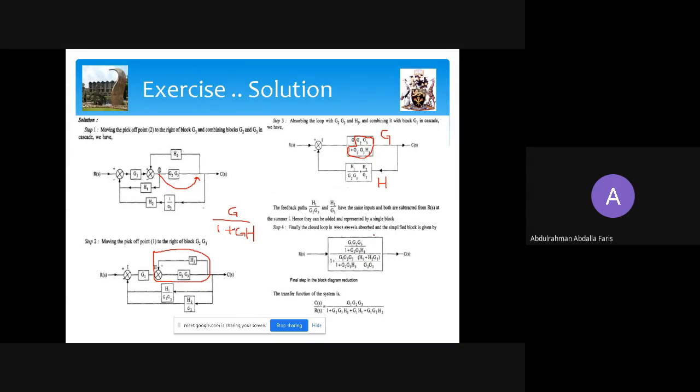So some guys actually did till here, which is okay, but you can first simplify. You can multiply 1 over G2, G3 on top and bottom. So if you multiply that, that will cancel, and if you multiply that, this will cancel. 1 plus G2, G3 will be here. So this one will be here. From here we have that, and then also these G2, G3, they can cancel there. You open this, you end up with G1, H1, G1, G2, H2.